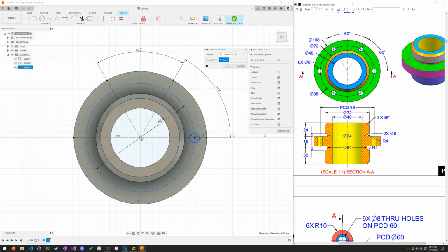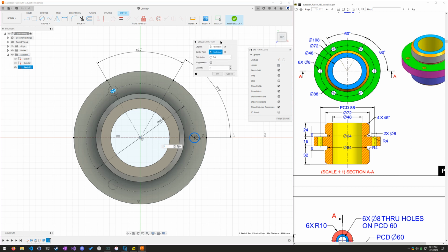using the center point as the origin, okay, bring this down a little bit to see more options. There we go. I want 6 of them. There you go. See, they automatically lay on those angles. So we really didn't even need these, but they're good practice to make because sometimes they don't want these evenly spaced. They want them on very specific angles. So, you know, practice drawing them. It's useful. All right, let's go ahead and click OK on that.